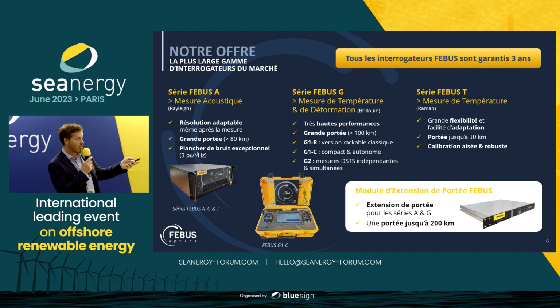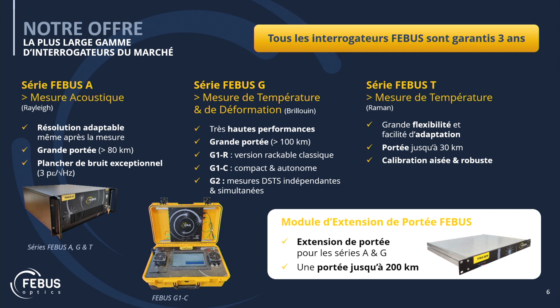That's the same way we can measure Brillouin, that's going to give you temperature and strain, static throughout the lifetime of the asset. And we can do it different ways, either a fixed or a portable version. So if we want to do some measurement campaigns, we take a suitcase, we go on site, we make a measurement, quite nice. And lastly, the Raman is going to be monitored through our T-series units, where you can get a much shorter range, but a more cost-effective solution to get temperature.